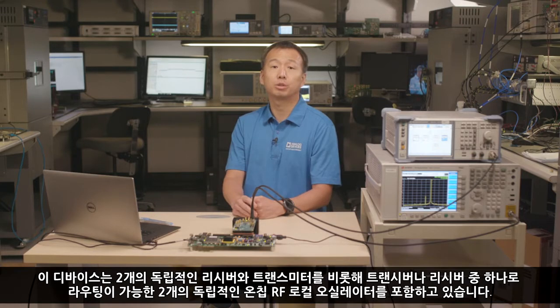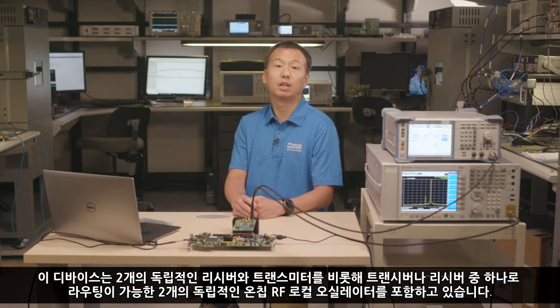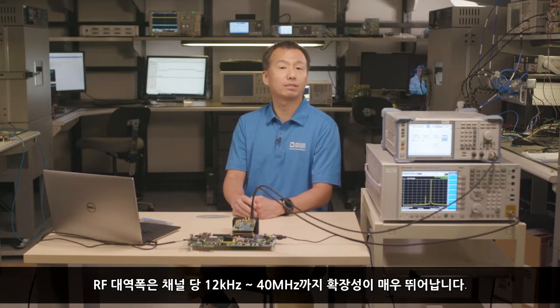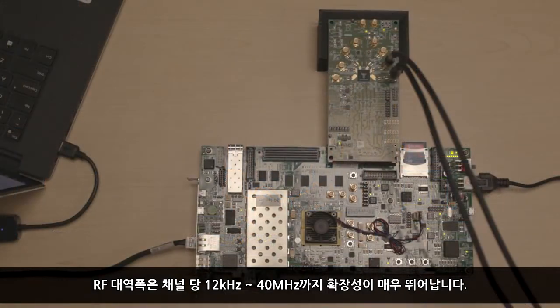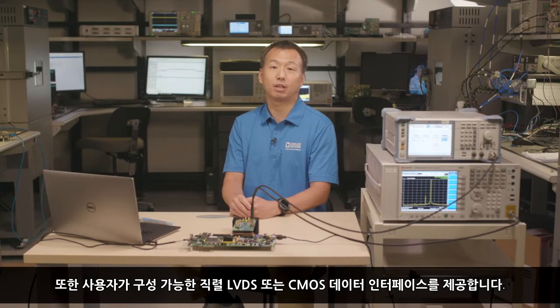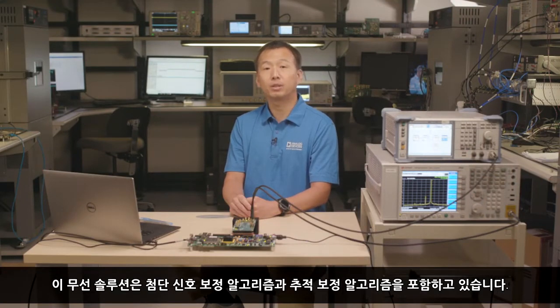It contains two independent receivers and transmitters, and two independent on-chip RF local oscillators that can be routed to any of the transceivers or receivers. The radio provides a wide RF tuning range from 30 MHz to 6 GHz. RF bandwidth is highly scalable from 12 kHz to 40 MHz per channel. It offers a user-configurable serial LVDS or CMOS data interface. The radio incorporates advanced signal correction algorithms and tracking calibration algorithms.